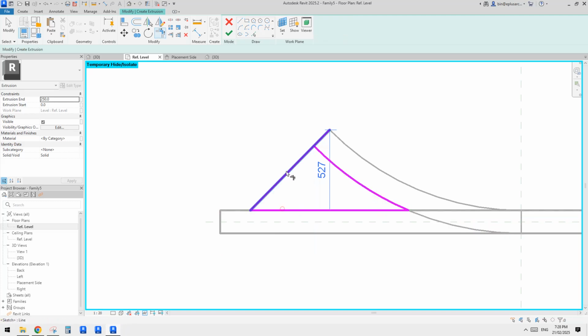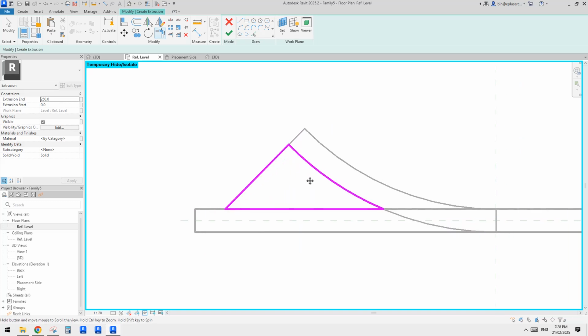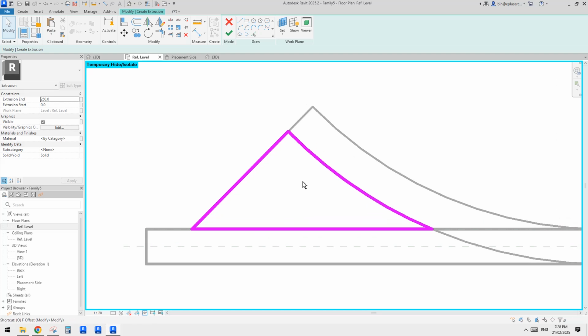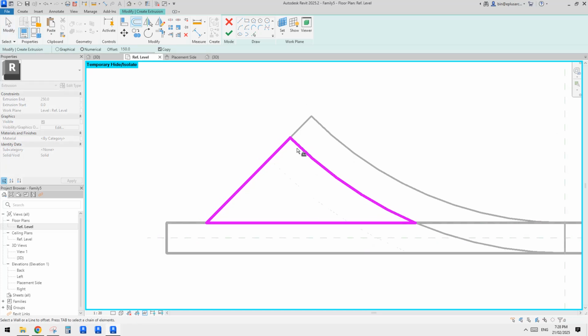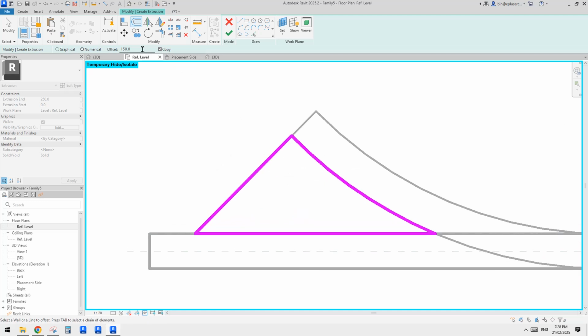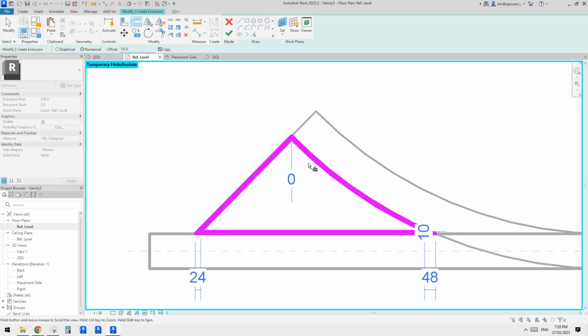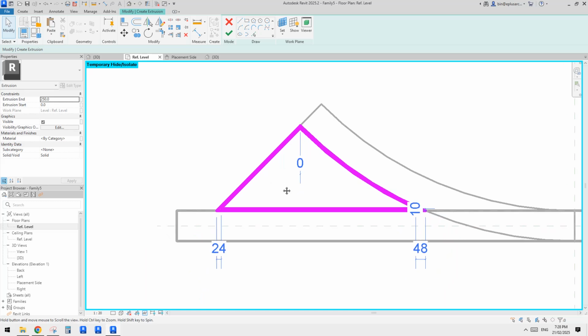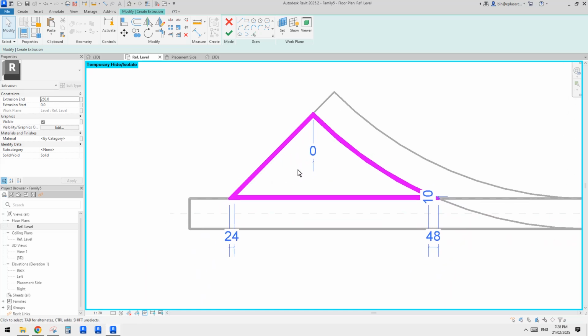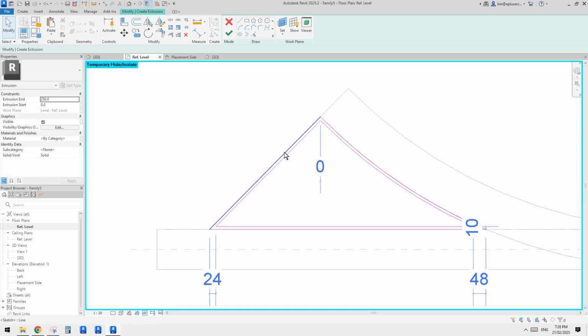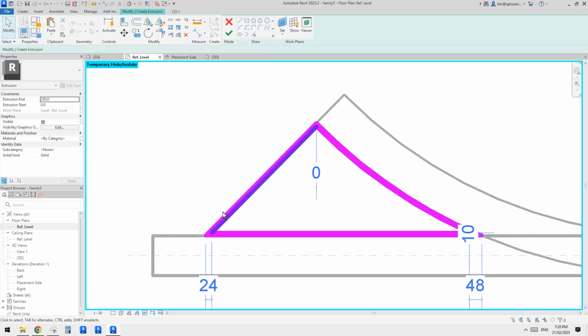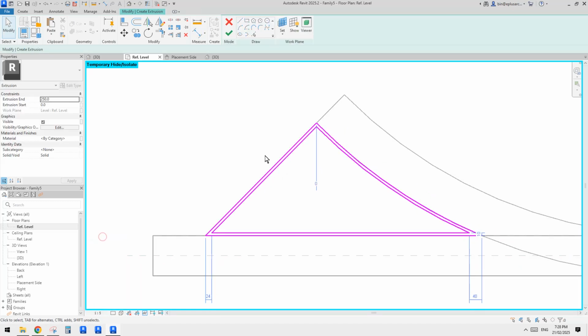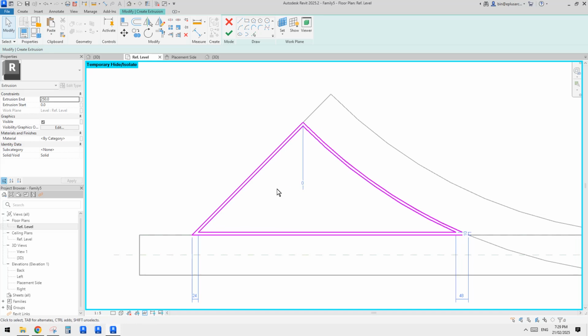Okay, I believe all these lines are fine, but now we will have an issue. If I do an offset, because we wanted to create like a 10 mil metal box, if I do 10 mil and offset from all this, I don't think there's any way we can just automatically lock our constraint. So let me just TL so we can see all the lines. Actually TL, change the scale so they are still relatively thick enough.